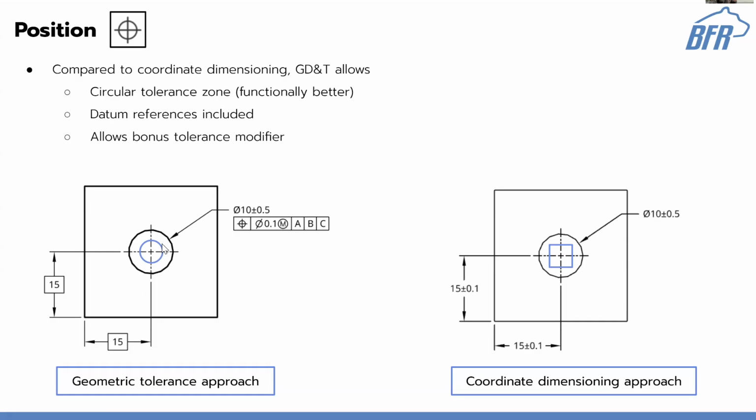So you'll set your tolerance, right? Right now it's 0.1 to whatever that bounding condition is. I'll say if it goes any farther out than this, then it likely won't go through the hole anymore. That's how I set the tolerance. But here you'll see I use a standard dimensioning approach. I say it's 15, probably millimeters, 15 millimeters off from any direction with 0.1 off, right?